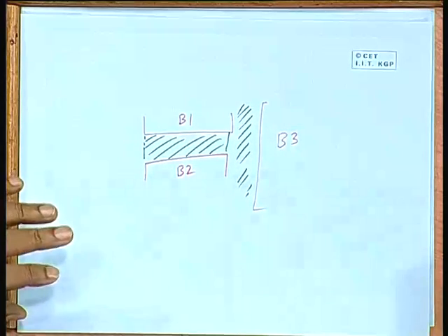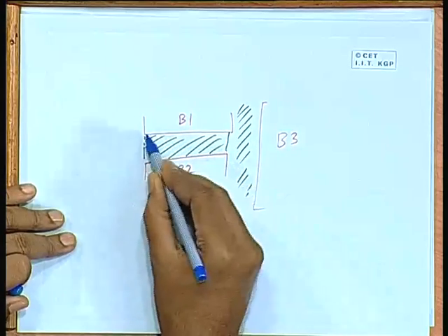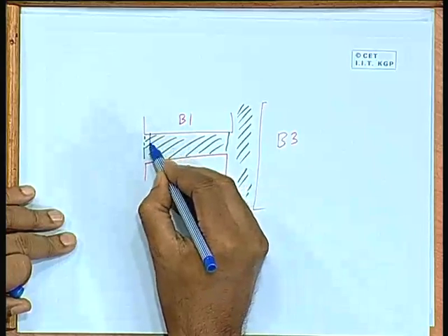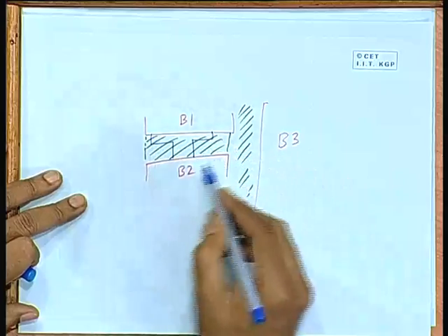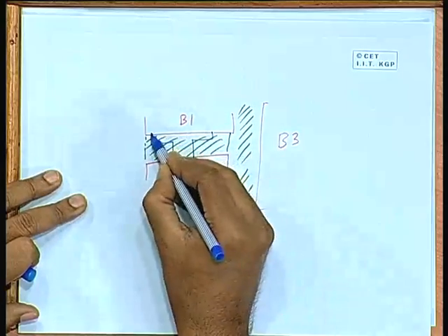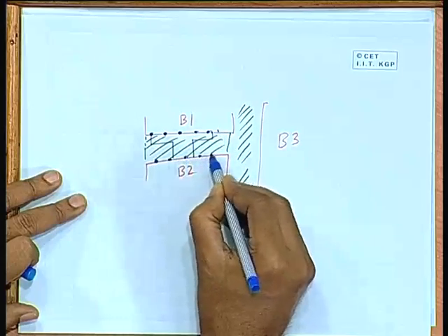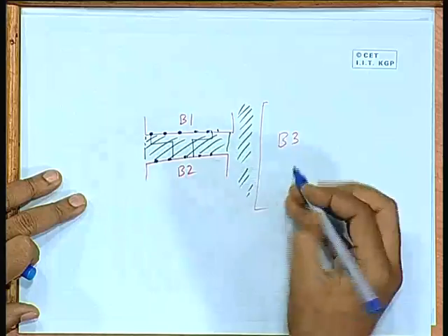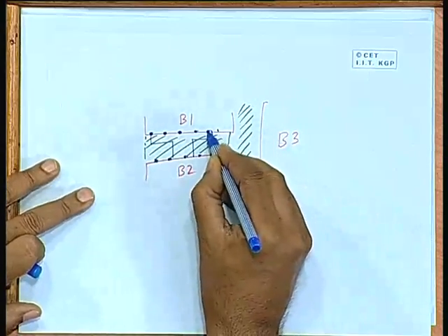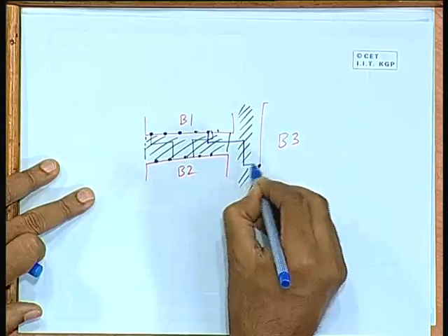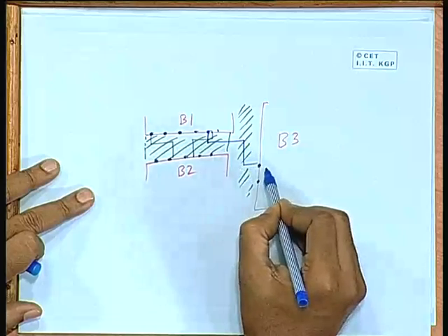Suppose we are considering the problem of completing the route in this region first. So, we will be trying to interconnect the points whatever they are. Now, it is not necessarily true that all of these interconnections will connect points of B1 to points of B2 only. There can be some nets which will connect B1 with some point of B3 also. So, those nets will possibly be routed like this. They will have to cross this region and enter the other region.